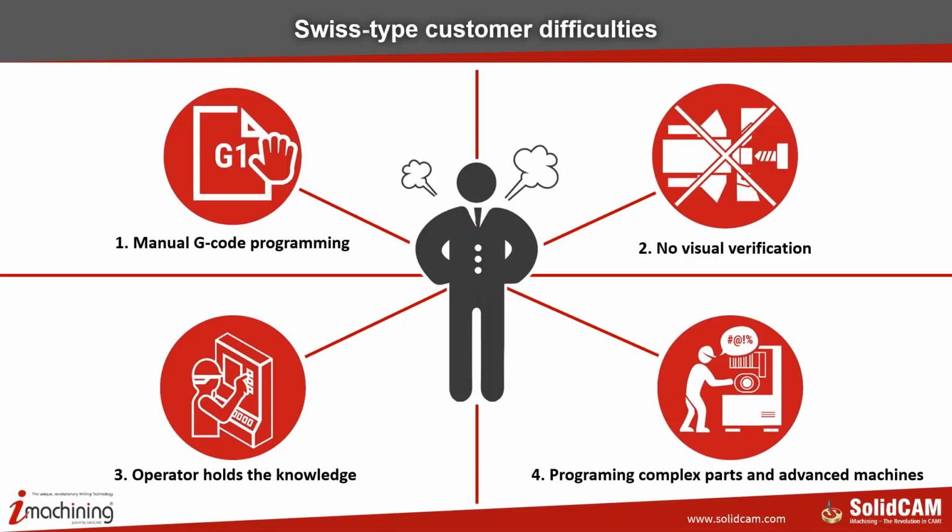There's a lot of G codes. Programming each one of those machines, it's really crazy. Yes. Besides that, today I can see on the market the machines start to be very complex with at least one B-axis. Recently I saw like 3 B-axis on one Swiss. So with those machines, you simply cannot program it manually. The only solution is to have a CAM solution.